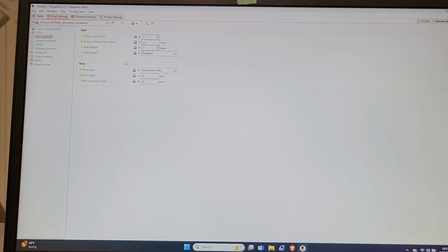And then the brim width on Cura, there's not really, I guess you probably could if you wanted to tweak specific stuff, but when you choose a brim on Cura, it's normally about a 10 millimeter width that it prints for the brim. So that's what I usually put. That's what I put on here too. It's just a good solid outline around the print to hold it down.